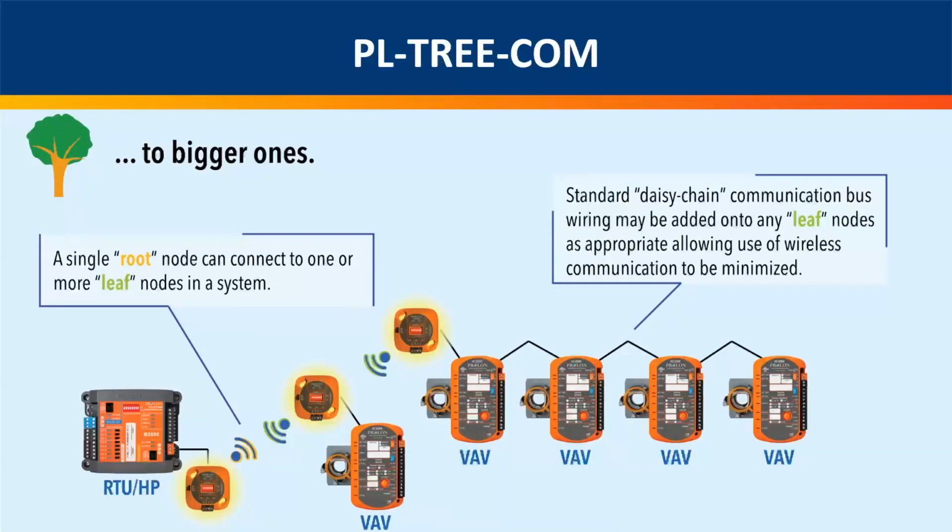Let's see, we also had one other question. Bob asked, what will happen to the dehumidification function when using dual enthalpy? The answer there is we can start dehumidifying using the economizer, but you will still have your mechanical dehumidification available if you need to.